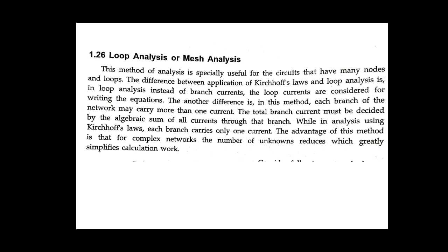So most of the applications are based on Kirchhoff's laws and loop analysis. So what exactly is the difference between Kirchhoff's laws and loop analysis? In loop analysis, instead of using the branch current, the loop currents are considered for writing the equations, and in Kirchhoff's law only the branch current is considered. Already we know what the branch current is and what the loop current is.